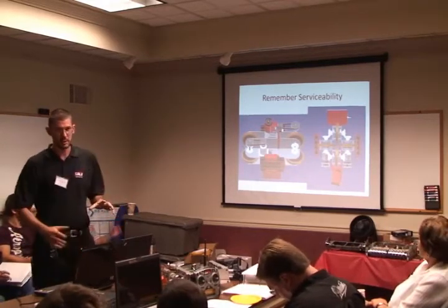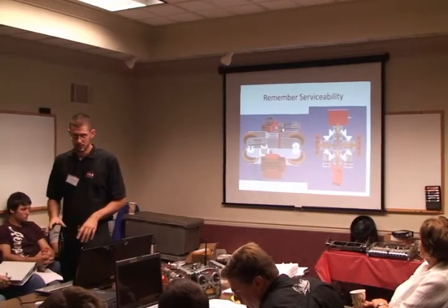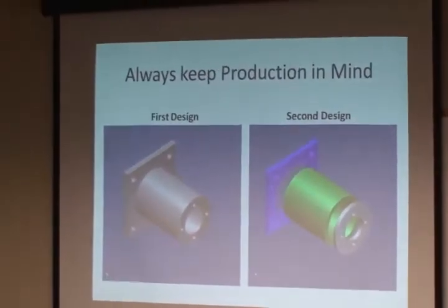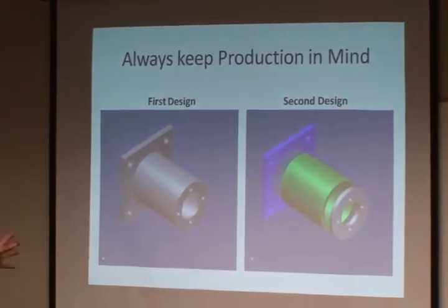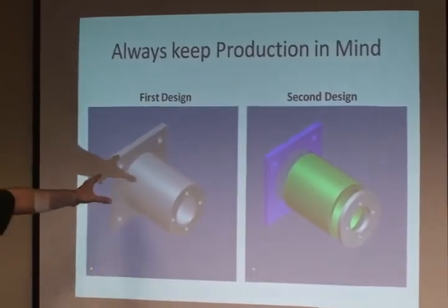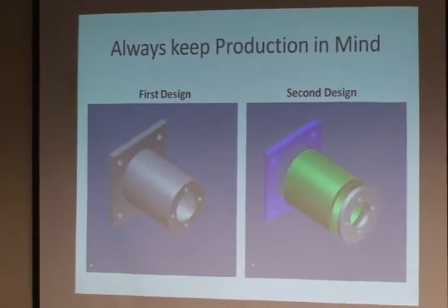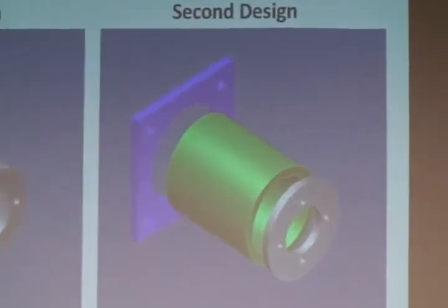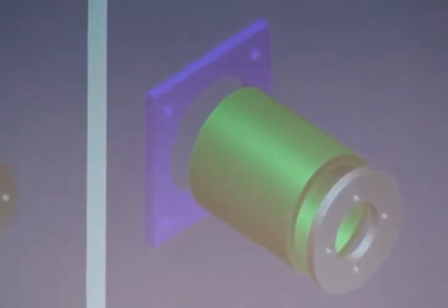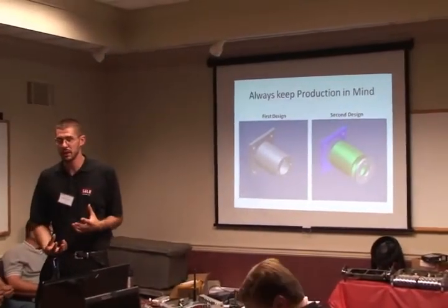So that's a little bit of experience that I've had with designing robots. And this would be something you would talk about in your refinement section. This is the motor mount for that robot. The motor sits inside here. We drew it on the computer as one solid part originally. Well, turns out that one solid part, we'd have to take like 90% of the material away from a solid chunk of aluminum to make that. And it was going to take multiple processes. It was just going to be so incredibly difficult to manufacture that part.